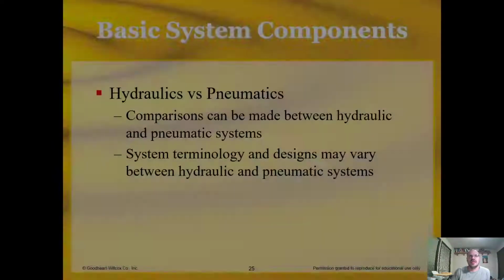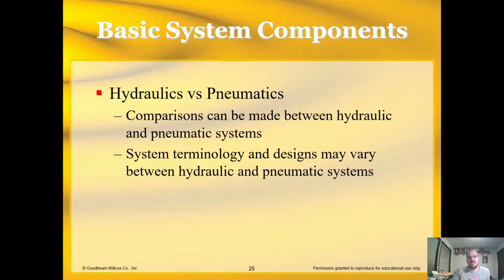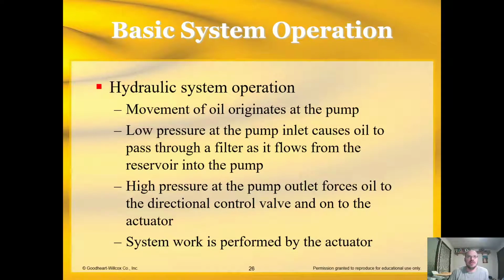Hydraulics versus pneumatic systems. So these are very similar, and actually a lot of even the graphic symbols are very similar. In this case, comparisons can be made between hydraulics and pneumatic systems. And I'll let you know when, there's a lot of those that can be made, but in some cases, you're going to have a variation. So system technology and designs will vary typically between hydraulics and pneumatic systems. Hydraulics is heavier than pneumatics. Your main difference there is compressibility.